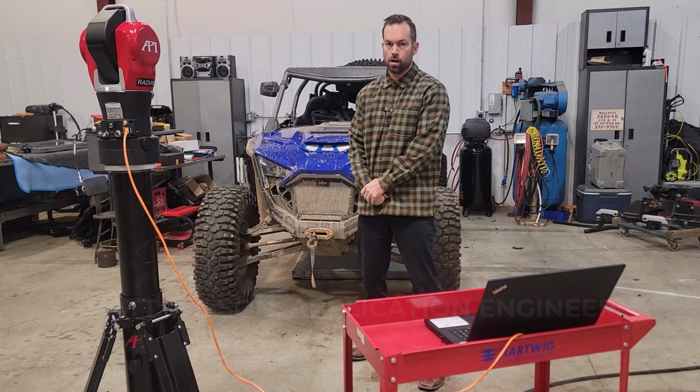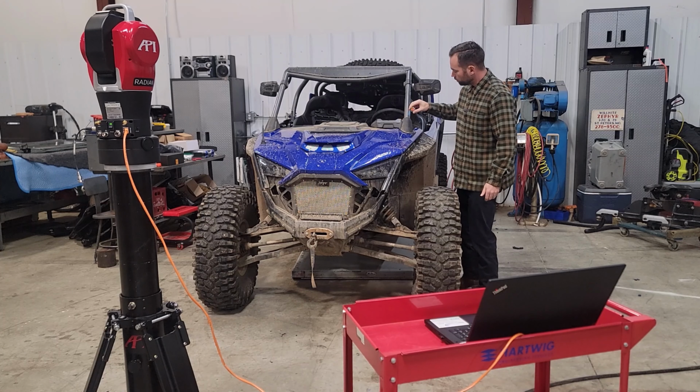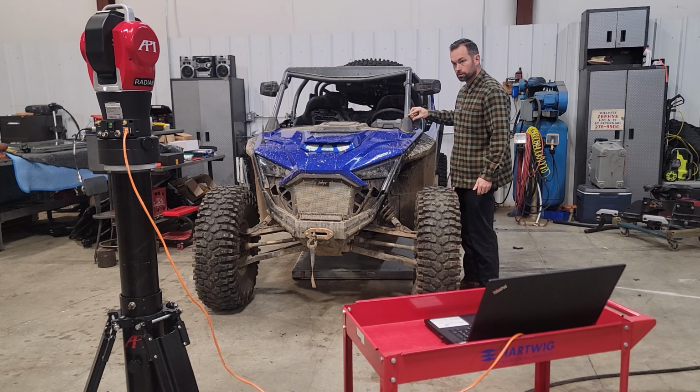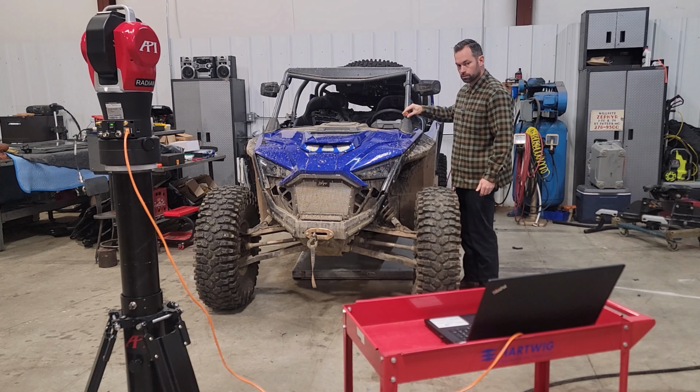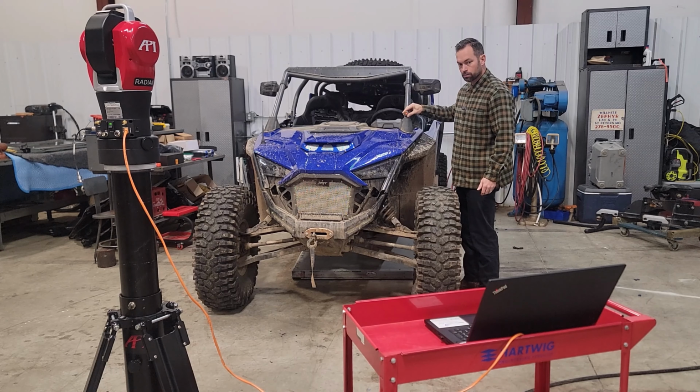I have my tracker set up. Nice thing about the tracker is you can have it set up using Verisurf with a smart point. So I have it set up to do smart point. I'm gonna measure some cylinders. I'm just gonna do 8 points. It's straight tube. So you can also set this up where you measure with your phone, or you can set it up where you measure with your Apple Watch.